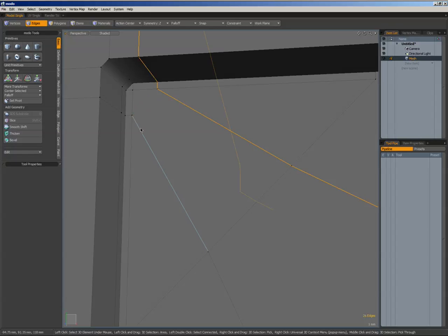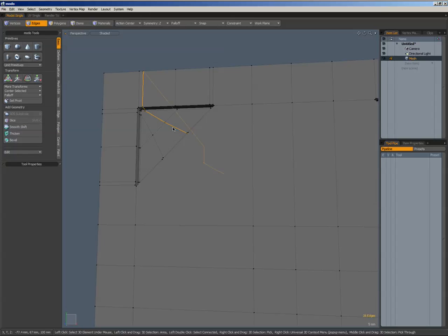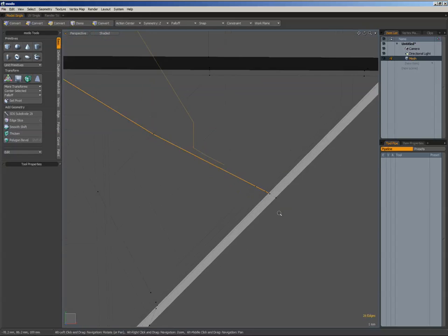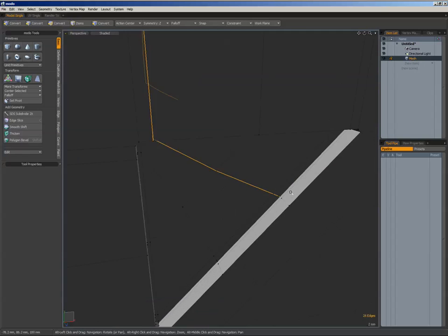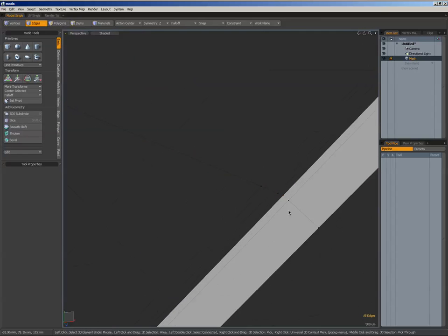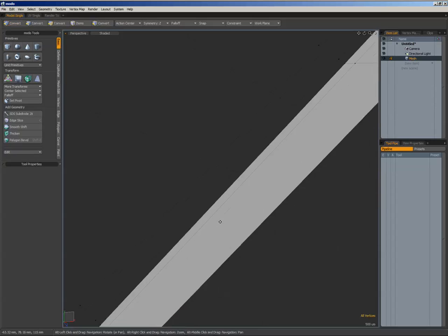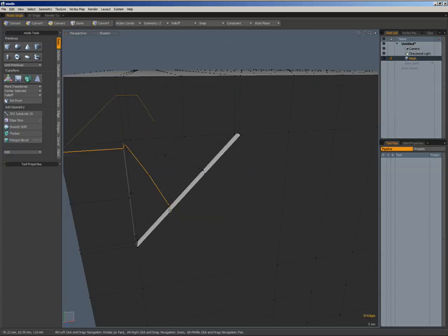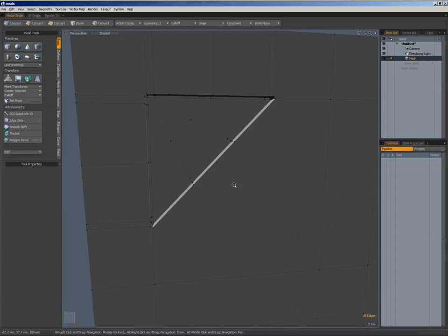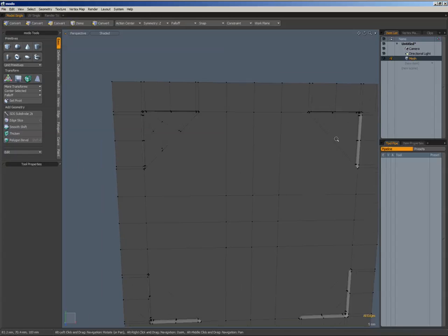Double click. Okay, fully edge loop still. Double clicking will allow us to see where edge loops terminate. And in this case, I missed one. So let's connect these again. The edge loops terminate right about here. Let's do the same thing here to these three areas down here.